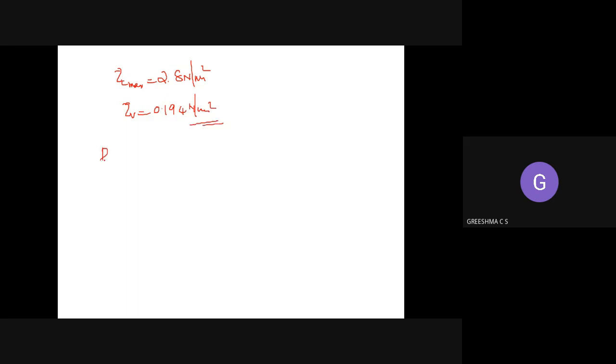Based on the percentage of reinforcement ratio PT. So PT is equal to 100 Ast divided by b into d. Okay, so which Ast will you provide here at first? Here we have 3 or 4 Ast. For the middle strip, 2 Ast come in x and y. At the same time, for the edge strip you are also providing minimum steel. So which Ast will we take?